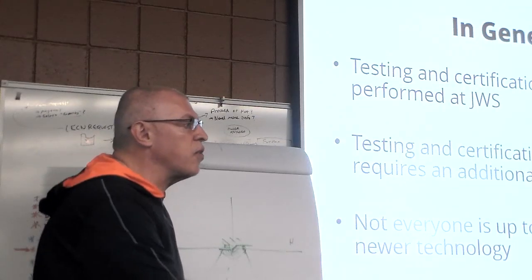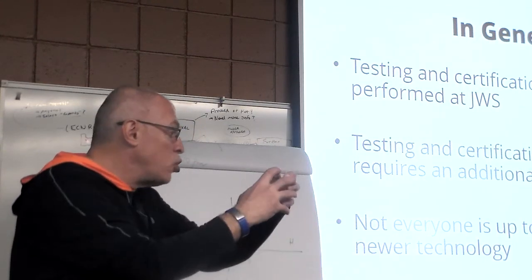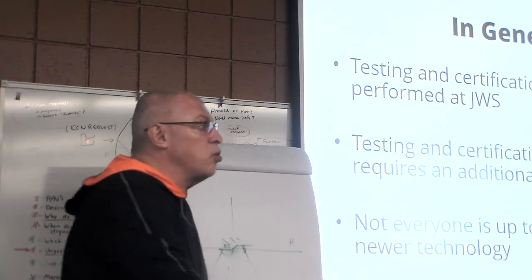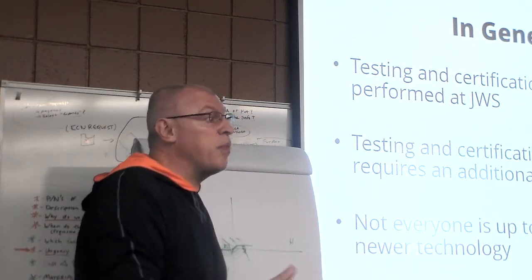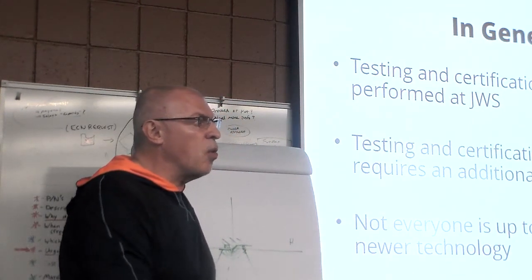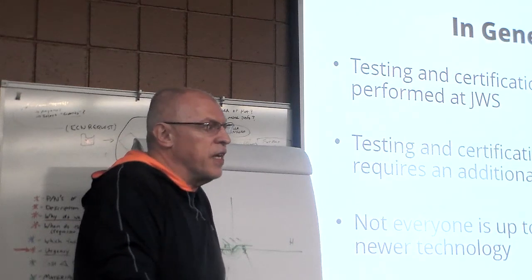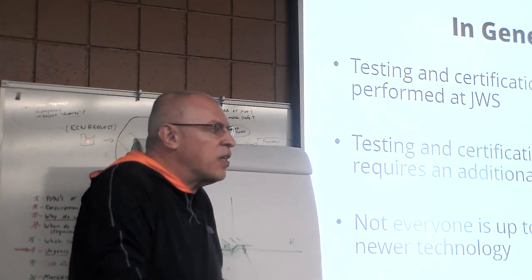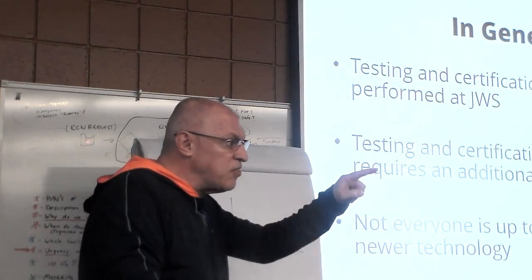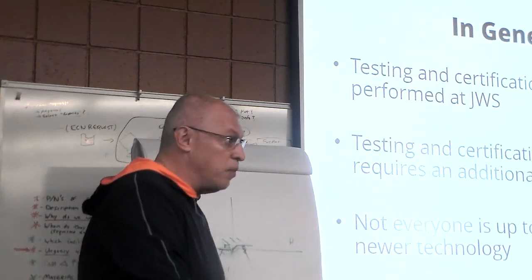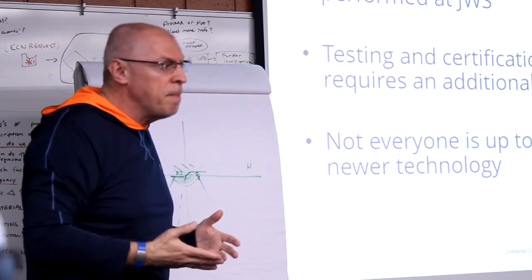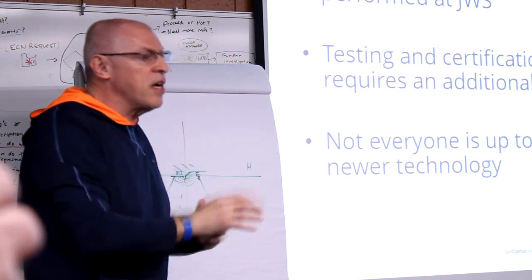There is no lingo for it, and it's a big debate how to do it. You can make a module, which is a low beam, and put it into a housing to be replaceable. But how do you certify that? What do we call it? Because FMVSS says replaceable bulb, and it's not a bulb, it's a replaceable LED. So they are particular there.